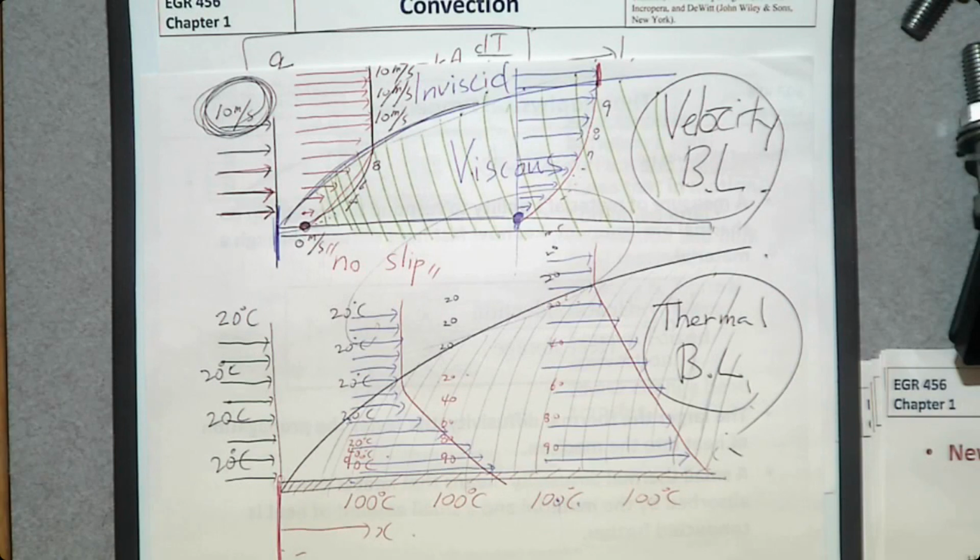So the convection heat transfer study is going to be in this form. We have an actual geometry, velocity, and so on, and we are going to convert everything into a dimensionless number and then solve the governing equation that is from an experiment, which is correlations. Then convert them back to the actual properties. So that is how we solve convection heat transfer problems. Okay, I'm just giving you a brief introduction about what's going to happen, because this is an introduction chapter.